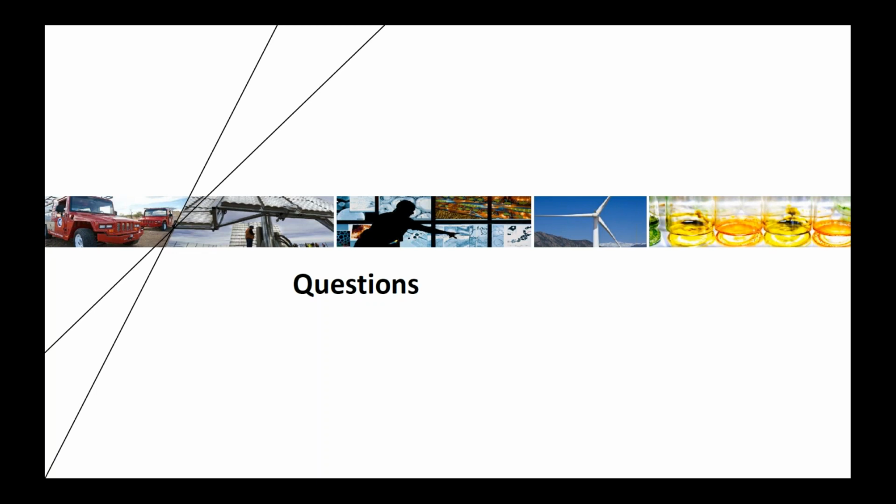So the first one for our experts today: eliminating blower-off delay seems like an easy, high-impact measure to reduce humidity excursions. Is there any downside to doing this? Can most systems be configured this way in the field? Would it make sense for manufacturers to change the default setting? Who would like to answer that question?